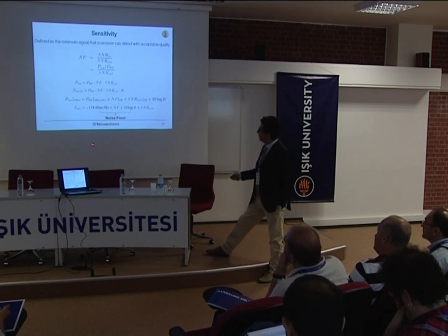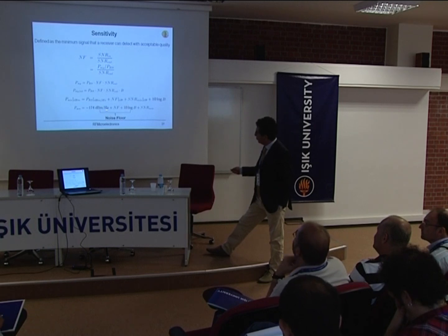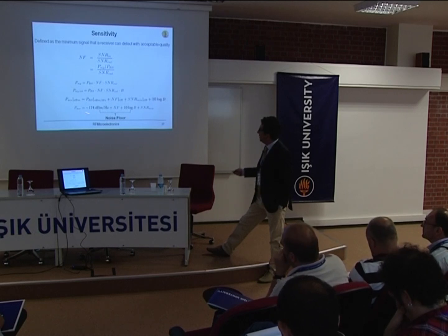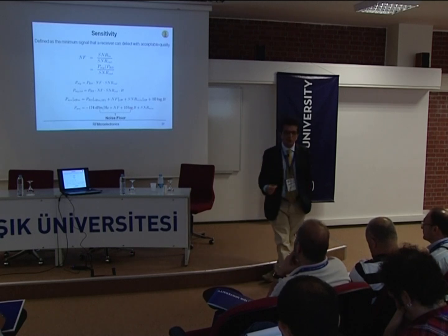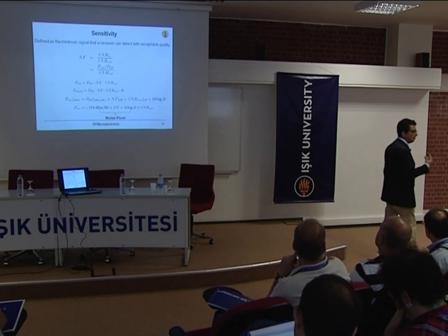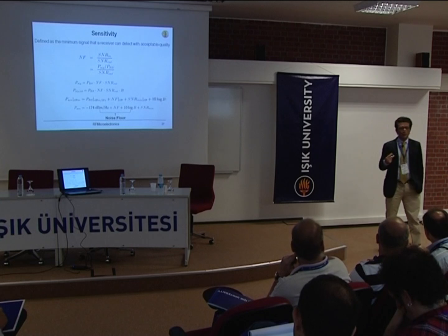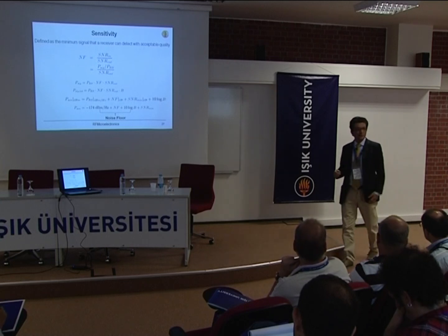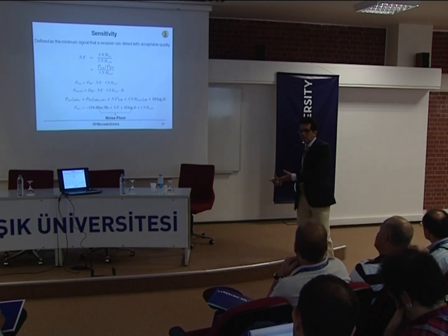Also, we can understand from these three contributions, known altogether as the noise floor, that the sensitivity for a given signal-to-noise ratio depends on the data rate. So knowing that a given application has some sensitivity doesn't immediately mean, if the applications are different, that a lower sensitivity reflects a better product, because it depends on the application for which it's done.